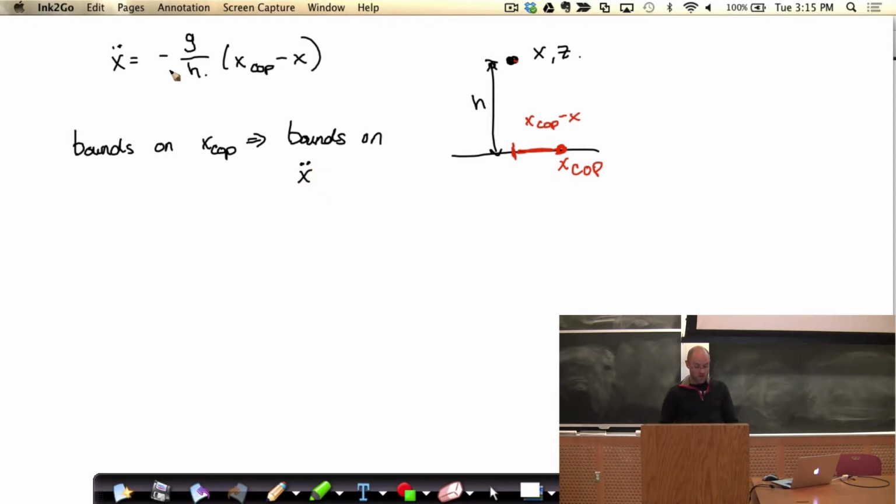And because it's a linear relationship, that's an easy mapping. What's more, it turns out this gives me an extremely simple way to generate feasible contact sequences and feasible plans for my center of mass relative to my center of pressure.